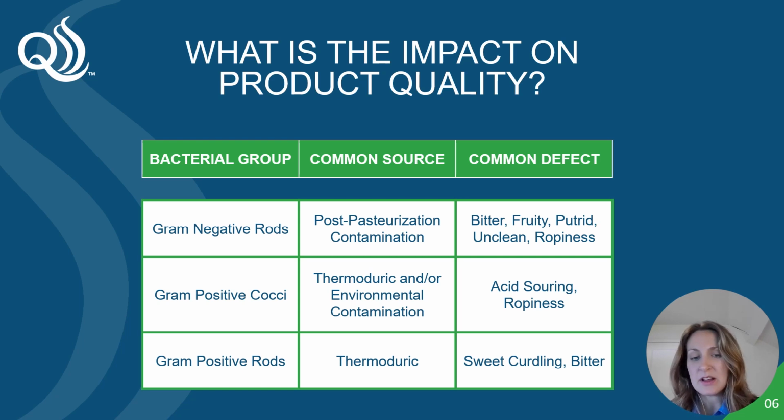And that can be a challenge if you're having a long shelf life, even short shelf life, if there's disruptions in your transportation process, or if you're trying to build conformity of your product across several sites. It's something that you want to make sure that you have good controls in place to identify those types of bacteria post-pasteurization, recognizing they could be coming before your pasteurization as well. You can also risk having pinholes, cracks, biofilms in your pasteurization step as well. And that can then also create other off flavors and defects in your final product. So you want to make sure that you're understanding that there's different types of bacteria being introduced in your process. And it can be at that kill step, but it can also be introduced ahead of them and then pass through that final step as well.